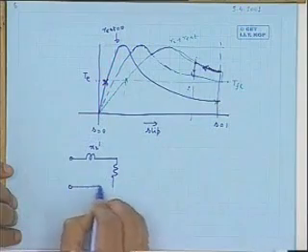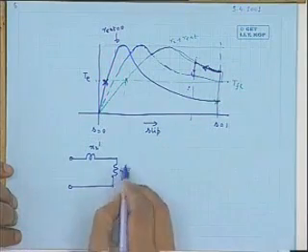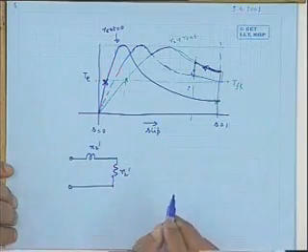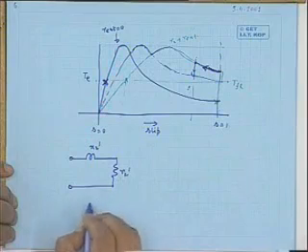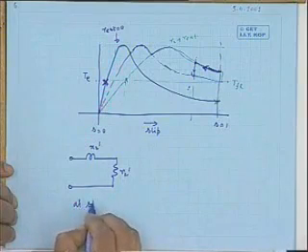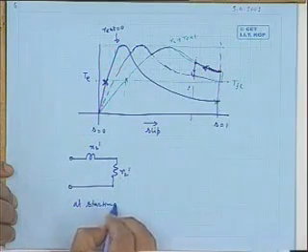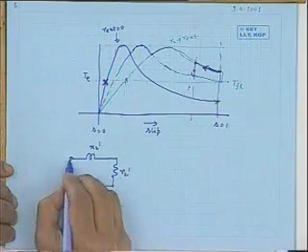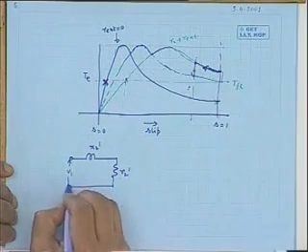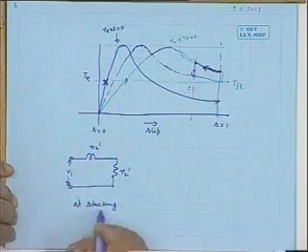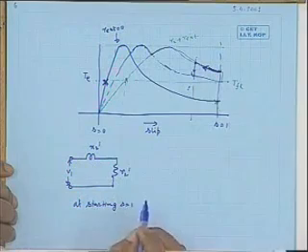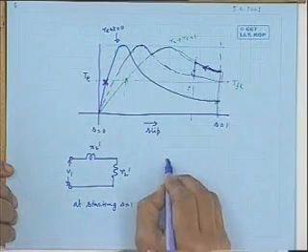It is X2 dashed. During starting it is R2 dashed in a normal machine, no external resistance connected. S equal to 1 at starting. And this is the voltage. So the current drawn will be V1 divided by this impedance at S equal to 1.